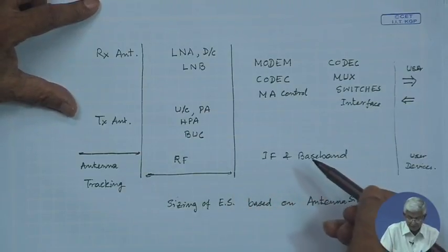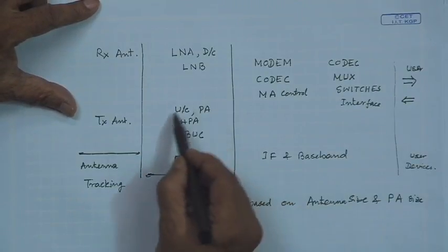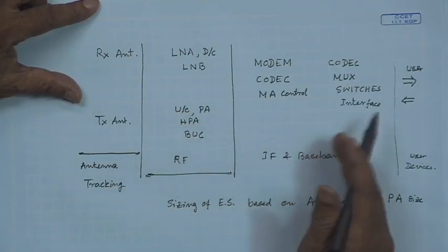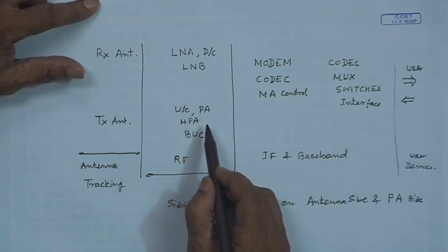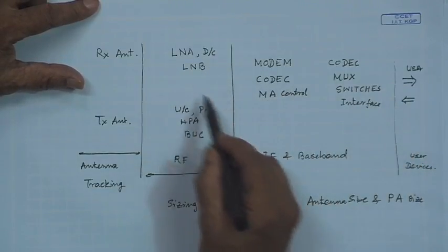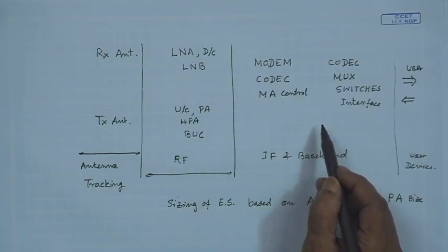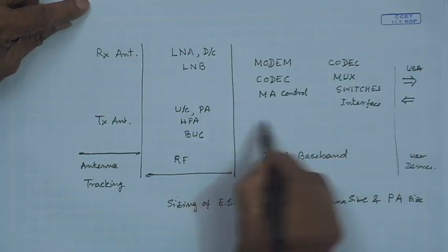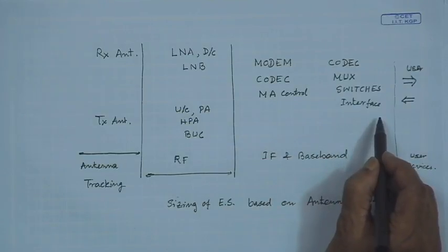Because if I have to transmit a larger power, the power amplifier is a dominating unit out of all these things; it draws heavy current. All other things are electronically realized nowadays in a very small area and small packages, particularly these IF and baseband, where people are using processors, DSPs, and sometimes, depending on the application or capacity, FPGAs and ASICs.